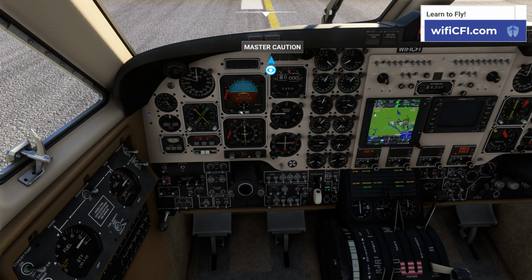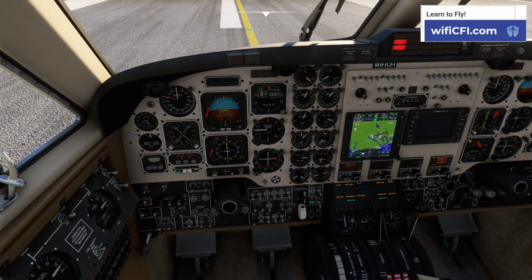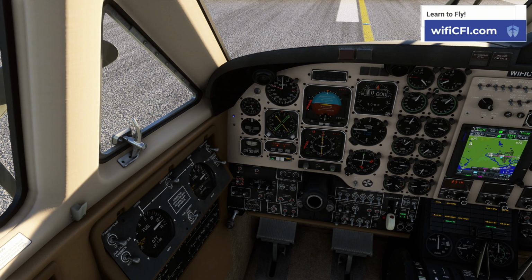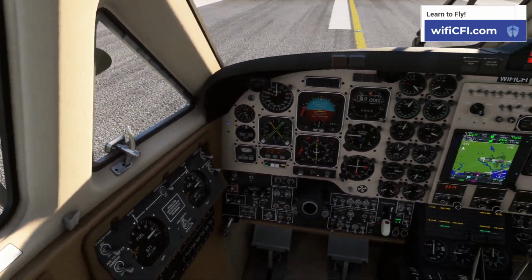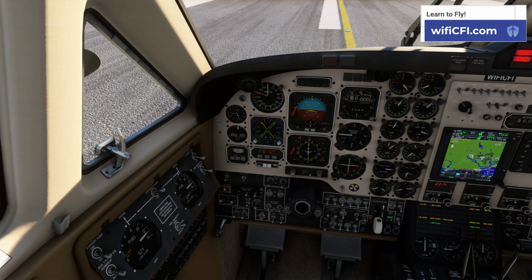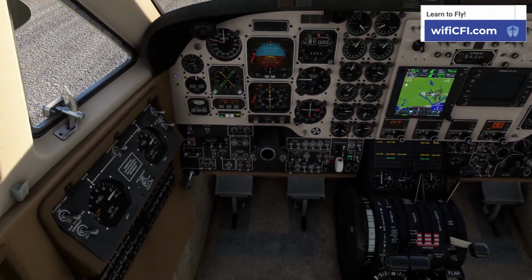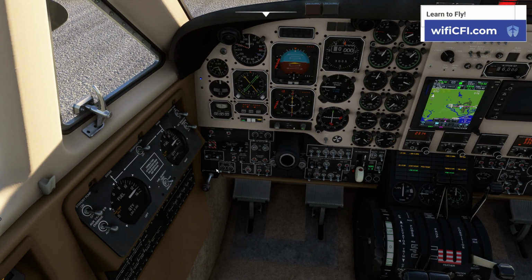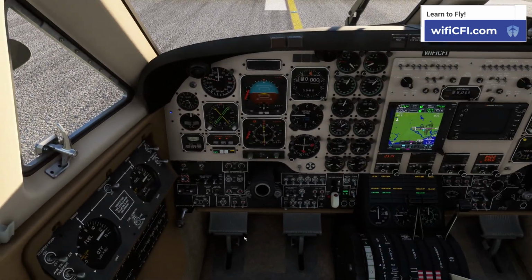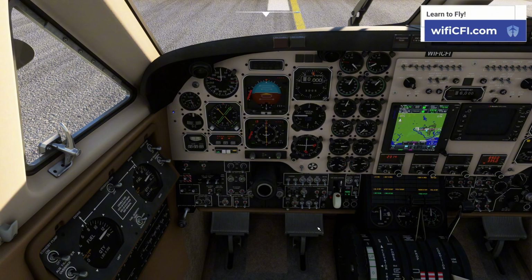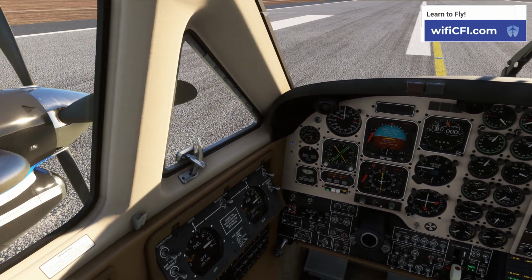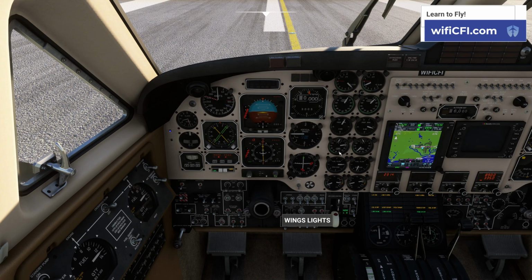And we'll just do a battery start on the left engine as well. On a lot of planes you can do it, I shouldn't say a lot of planes. I know on some models you can do a generator assisted start. I'm not sure exactly how it works in the sim, so we're just going to do 2 battery starts. Left, coming up. We can see our left engine ignition light is on and N1 is coming up. Got to get at least 12%. Got to wait for it to stabilize.